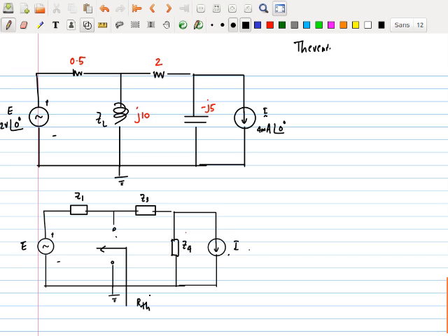Look through this to first of all find the Thevenin equivalent resistance. Now tell me, if it was a DC circuit, what would your first step be? Eliminate all the sources. What do you do? Short circuit sources. I just take a wire. Is that it? There are different forms of sources. You got voltage sources, you replace them with a short circuit, so that the internal resistance becomes empty. And if it is a current source, you open circuit it. Same rule applies.